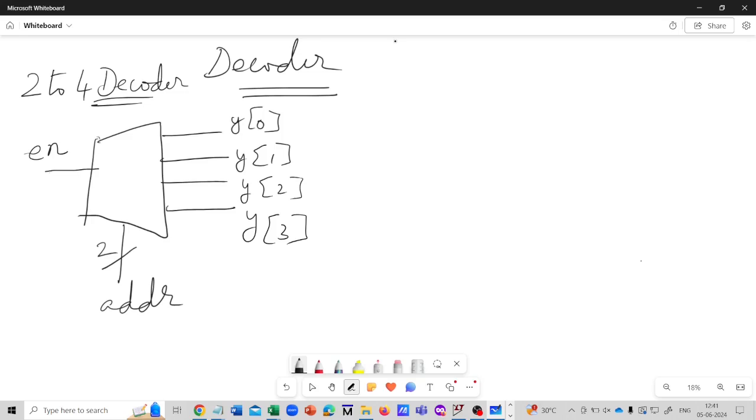Therefore, there may be glitches, there may be switching activities that propagate to the logic inside the decoder and reach the output, unwanted spurious transitions. These transitions may not cause any functional issues, any malfunctioning will not be there.